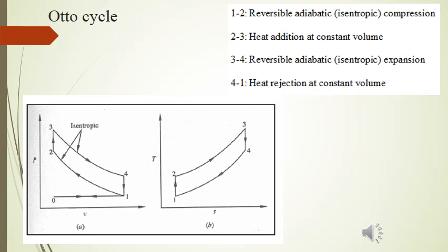And as the system has been modeled as closed system, therefore the energy calculation can be done easily by the first law, that is with the help of equation δQ is equal to dU plus δW. So basically from the point 1 to the point 1 again, that is involving process 1, 2, 3, 4, 1, the system can be modeled as closed system, and this is basically the thermodynamic cycle.